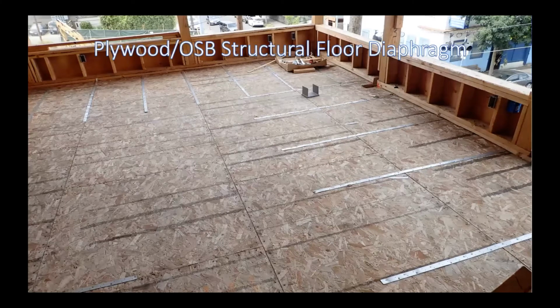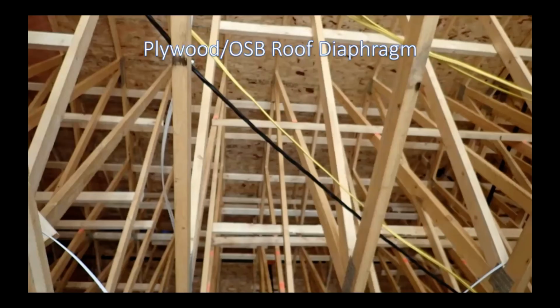Apart from shear walls, shear panels, you have to have decent diaphragms. And the floor diaphragm is something we see quite categorically over there, done with OSB or plywood in some cases, but predominantly OSB. Our normal particle board, chipboard, is not really a structural material. It's good for domestic construction, but when you're talking about large commercial structures where you want a dedicated diaphragm, you really should be looking at a dedicated structural product. And any structural ply or sheathing material is a good form to use. But over there, OSB is very, very common to be used as a structural floor diaphragm. And naturally over there, they cover the whole roof in the same OSB to provide a structural roof diaphragm to encompass the whole structure and thereby create that eggshell shoebox effect that I talked about.